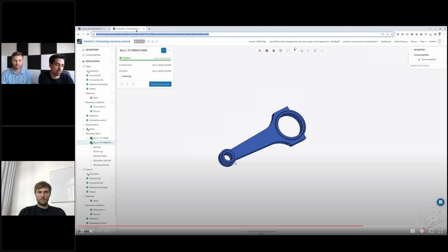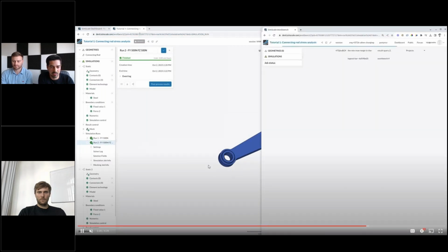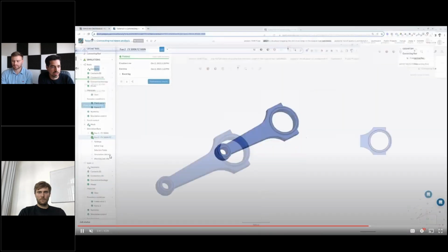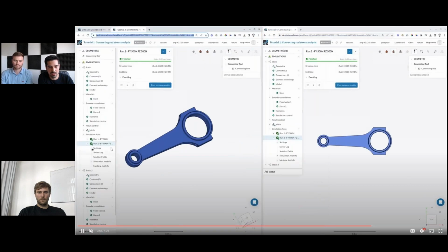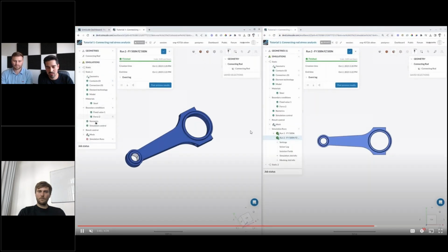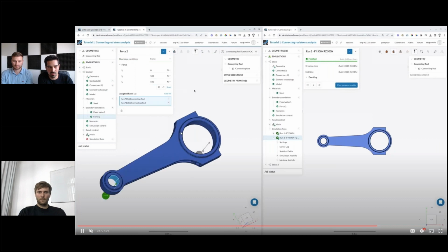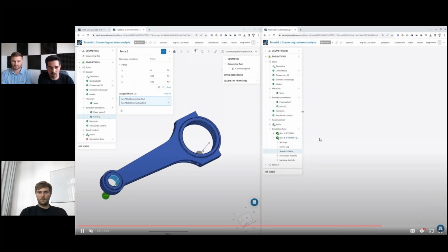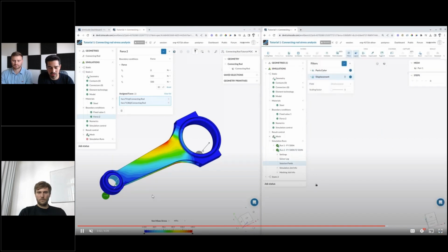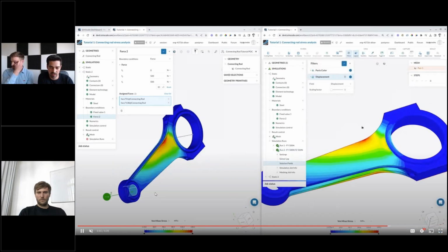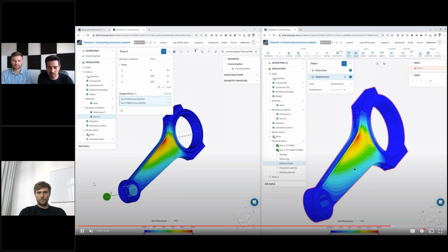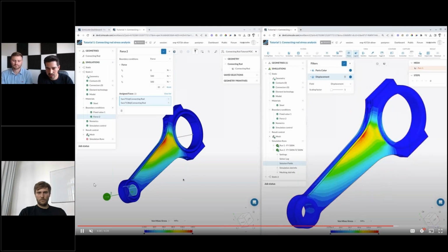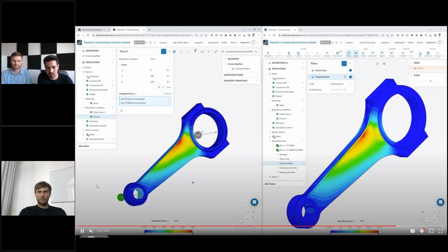So that's why we had here already some predefined results. So this is now the use case on the right, the simulation result on the combined use case 500-500 in Y and Z. And let's open the result and see if they roughly match. So we can already see the patterns look very, very similar. The peak stresses are also in the same spots, and also the ranges are pretty close.